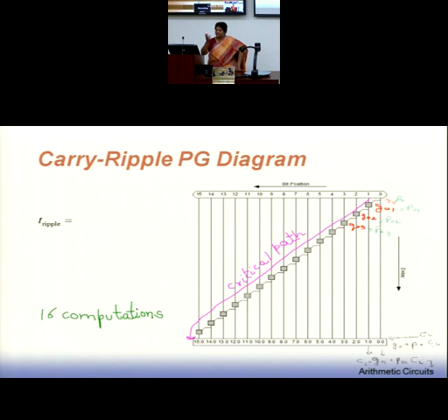You have to make Radix a variable. Accordingly, you have to define your delay equation, then minimize it with respect to Radix, and then find out the condition. For each adder, we would have a different optimum Radix value. Yes. But choosing an optimum Radix is also one of the ways of reducing the depth of the tree.